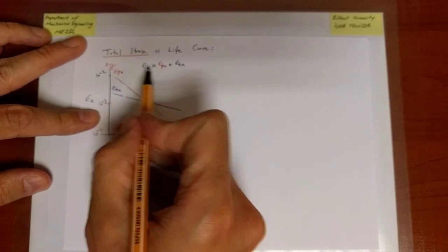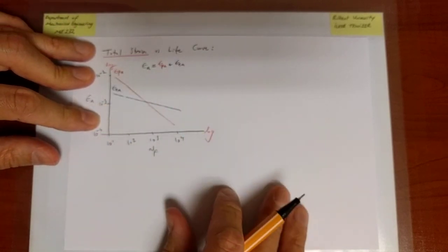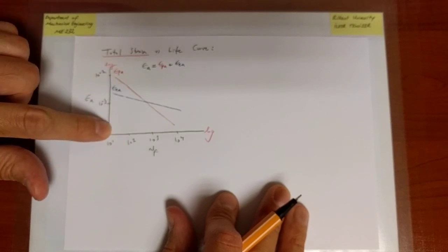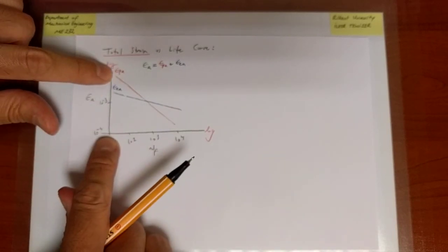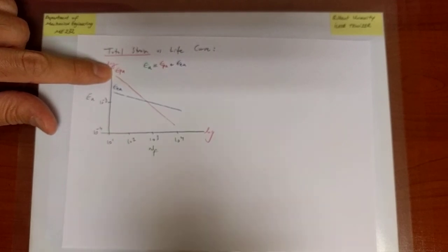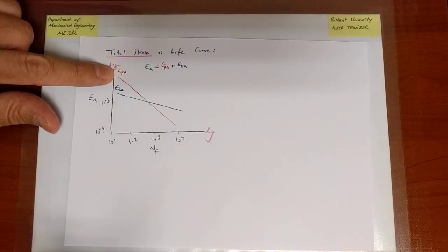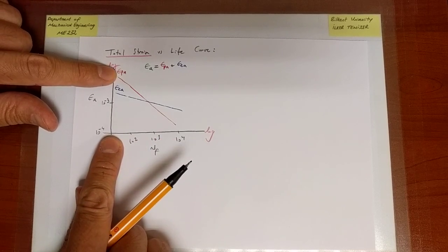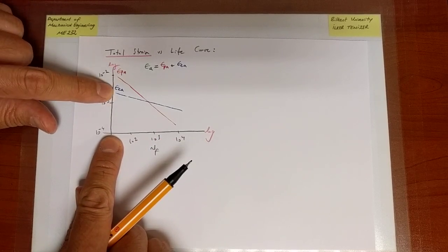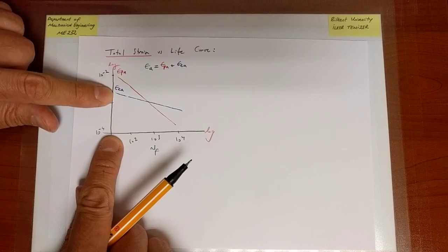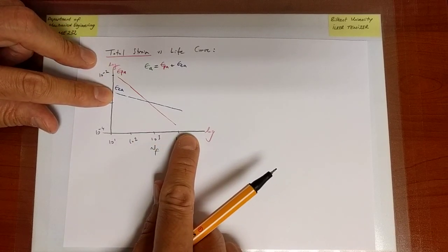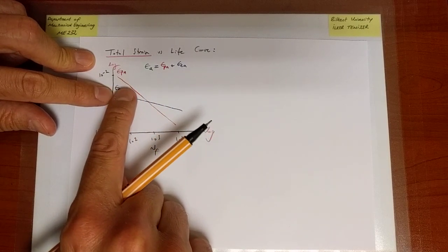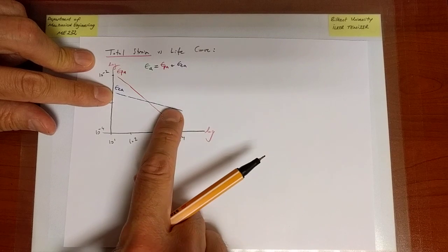So if we sum them and draw the corresponding line, first of all, when the life is very small, we notice that the plastic strains are very large. So we are observing essentially that when the life is very small, plasticity is much more significant compared to elasticity, so red is above blue, whereas if number of cycles to failure is increasing, we see that that is accompanied by smaller plastic strains compared to elastic strains.